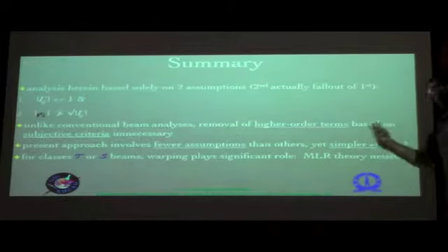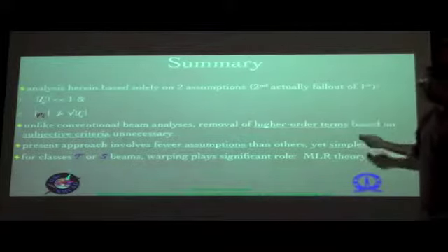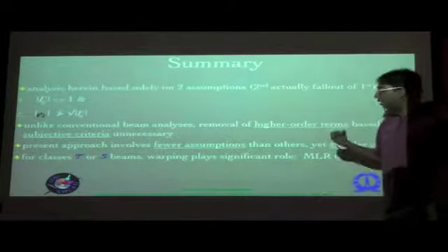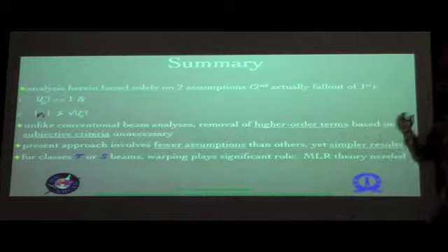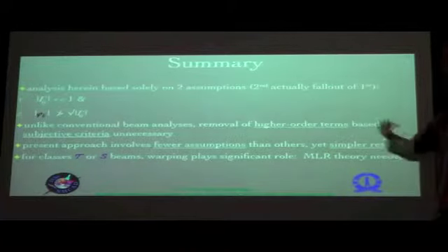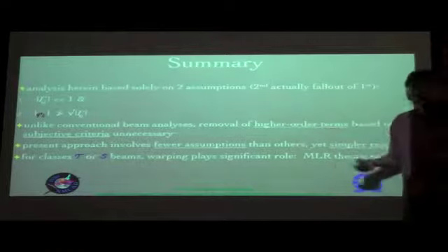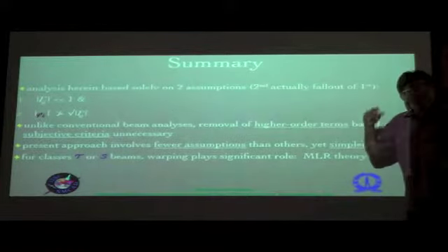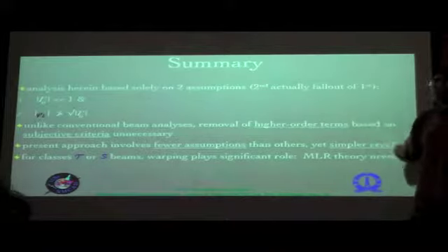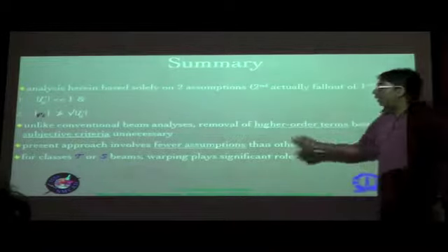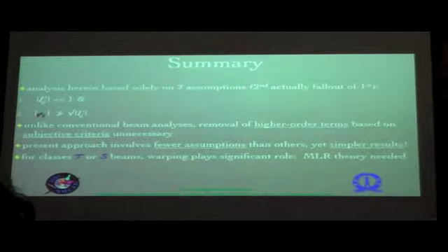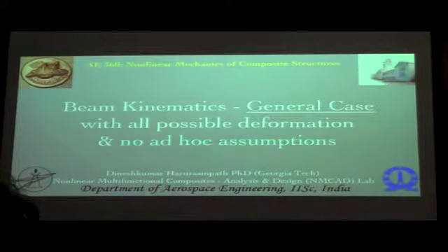And that aspect also we have seen, because we derived the whole deformation gradient matrix in mixed basis, and then we saw its antisymmetric part, which is the local rotation, and therefore its contribution to the strain in terms of three additional terms involving phi tilde squared as well as products of E with phi tilde, and their contributions also we looked at in the previous class.